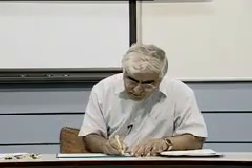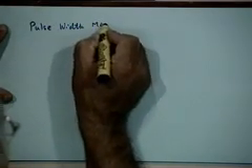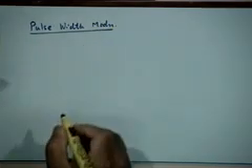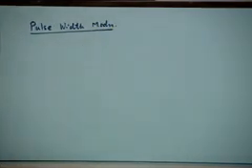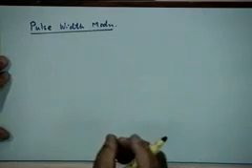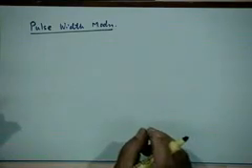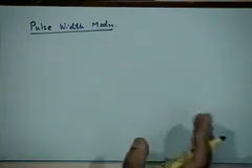More importantly, we will now turn to the two other kinds of pulse modulation schemes that are commonly used, namely pulse width modulation and pulse position modulation. Let us look at pulse width modulation first. As the name obviously implies, the parameter which you modulate here is the width of the pulse. That is, you want to make the instantaneous pulse width at each pulse duration proportional to the amplitude of the message signal. So, that much is obvious.